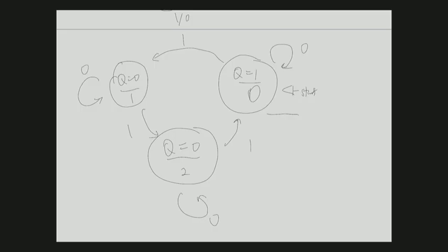The second thing is about the output behavior. By definition, the machine should output a 1 when the number of ones is a multiple of 3. Output is always a 1-bit output. You're using 0, 1, 2; these are more like the numerical meaning of the 3 states, not the actual output.